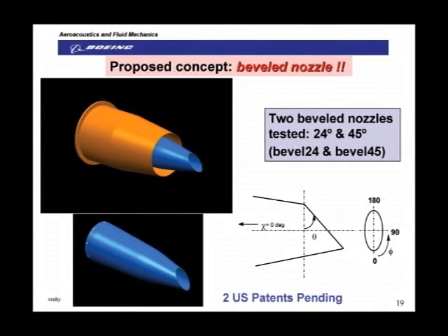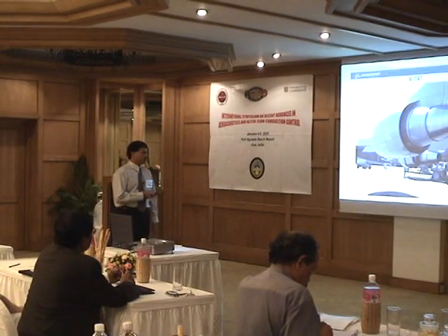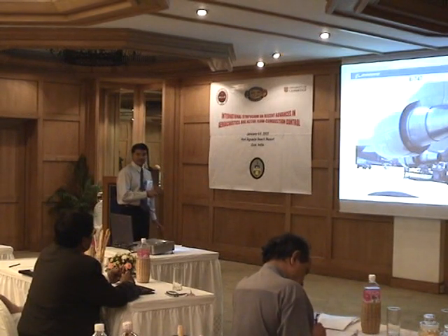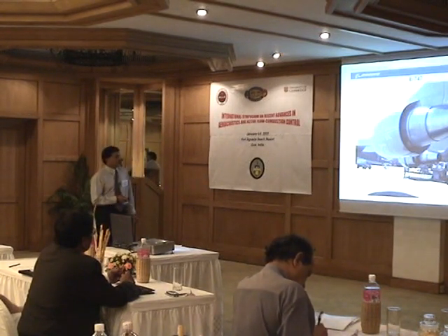Now, I would anticipate significant azimuthal content for this because your exit profile, when you look from the end, is not circular. It will be some form of oval. So we need to map the azimuthal content of this nozzle. So for this purpose, let me go back. Let me show you a close-up of this Boeing 747. What I'm proposing to do is leave everything alone and just go and bevel the primary nozzle alone. And there are very good reasons for doing that.